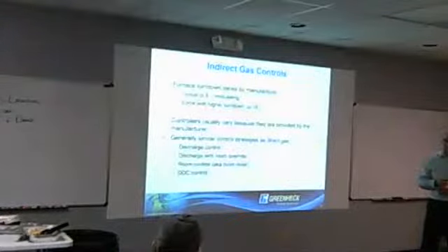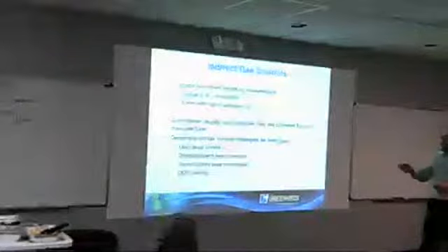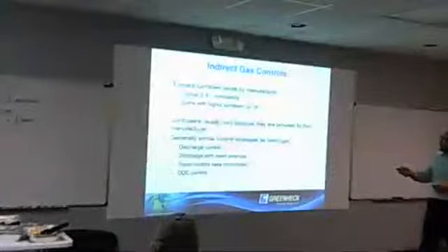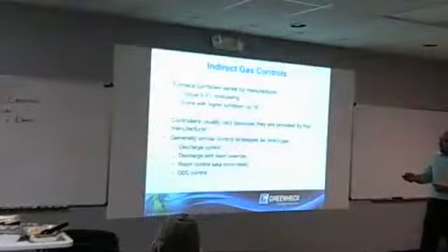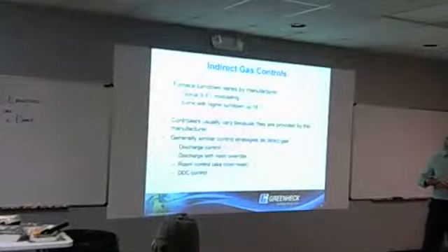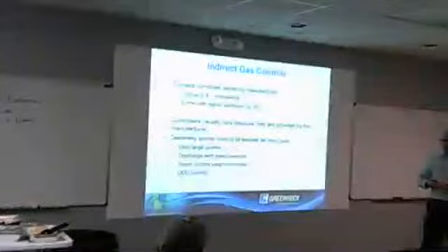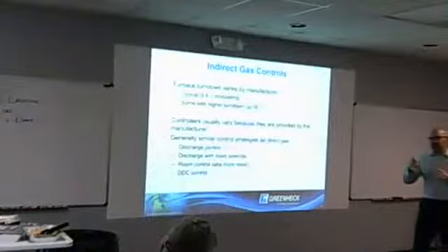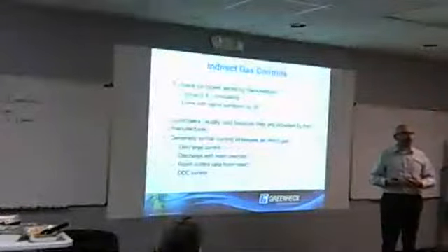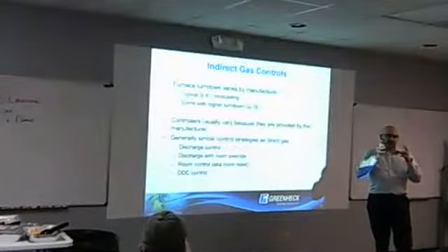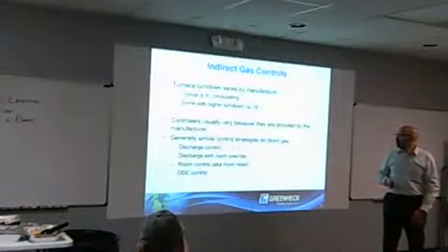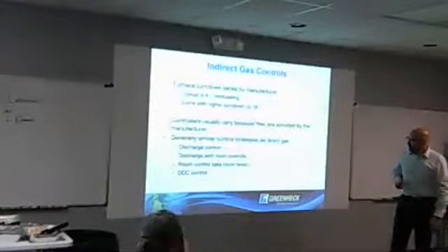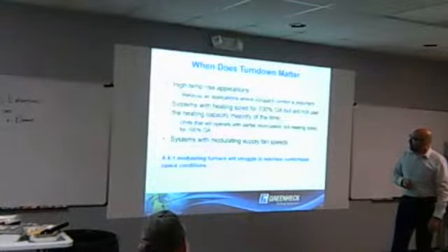So in terms of what will be coming up after indirect, we talked about modulation, 4-to-1 standard, some we can go up higher, as high as 16-to-1. And the controllers, basically the brains of the unit, are what's going to drive this. We prefer to control the modulation. Greenheck purchases, I think it's Maxitrol and some other modulating burner controls. If we let somebody else do it, then they really have to know the sequencing. It's not impossible, but we like to keep that within the controller that we can provide and program.